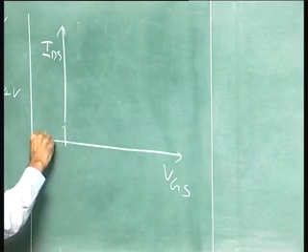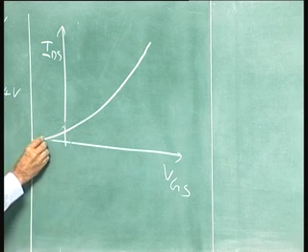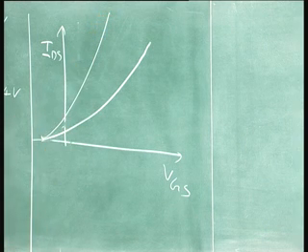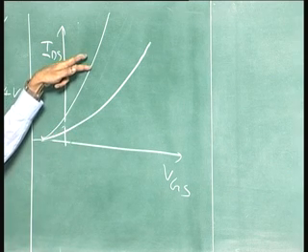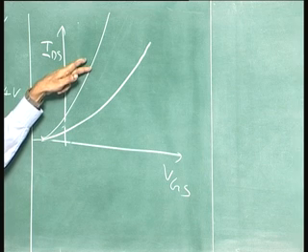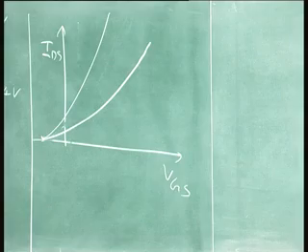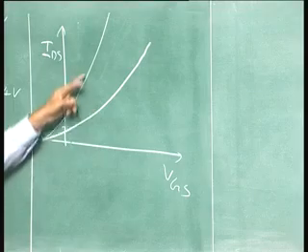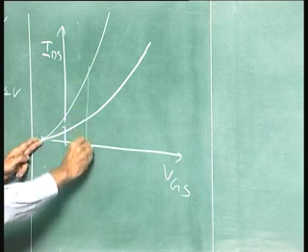That is the square law. If the threshold voltage remained the same, you would have got it like this, because for the same change in the gate voltage, the current is much more: (VGS minus V threshold) squared into mobility or other terms. Mobility is better.